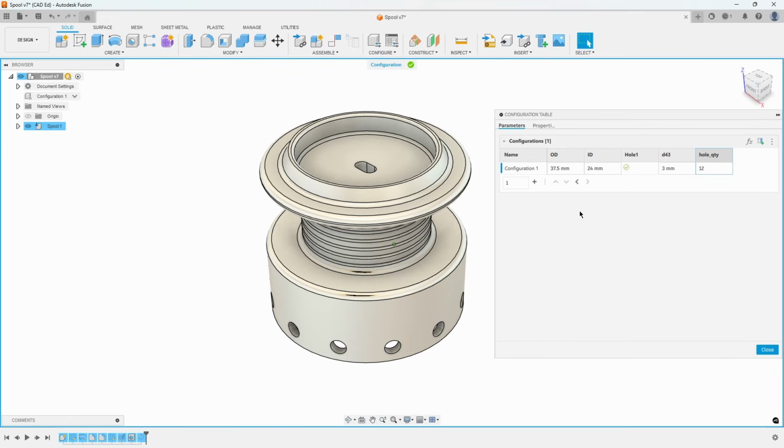Notice how the table is being built out with all of the options we have selected. The hole diameter column can easily be renamed by right-clicking on the column and selecting Rename Column. Change the name to hole_diameter. We can also rename the configuration to Original by right-clicking on the configuration name and selecting Rename. Refer to Exhibit 2.